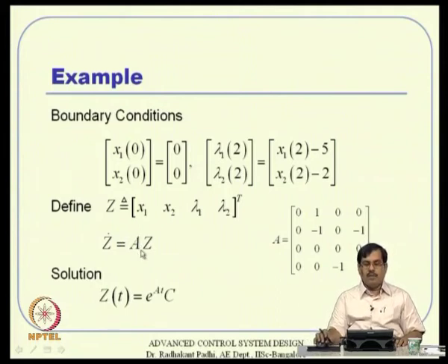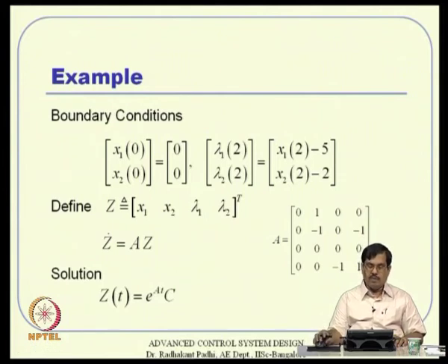Now, obviously what we have here is a linear homogeneous differential equation in state space form. So, the solution is z of t equals e to the power A t times c. Now, typically when you study linear systems solutions, as we have seen before, if you know z0, z of t0, then c is also z of t0 or z0, and you are done.